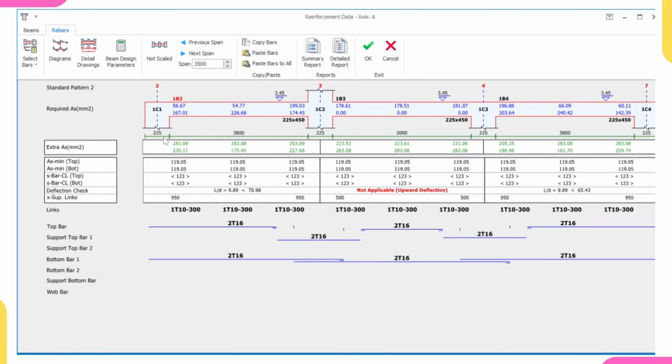Make sure you hinge it to save cost, to reduce the moment coming on it, because assuming with no hinge, here will be something like this 119. So that's the advantage of hinging your member. You can see here that with no hinge that is also 2Y16, but don't forget this is a residential building. Assuming now you're working on a commercial building, you will see this thing will be failing. But anyway, don't worry, let's continue.